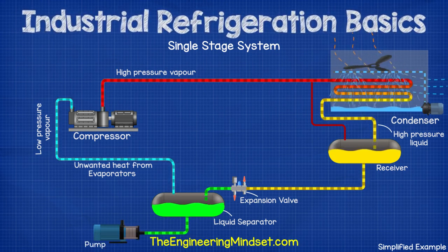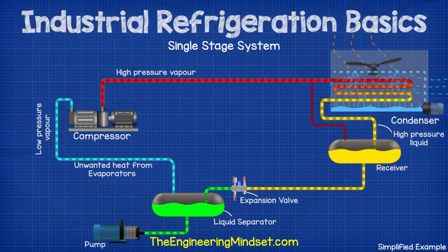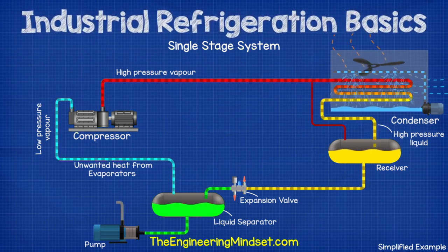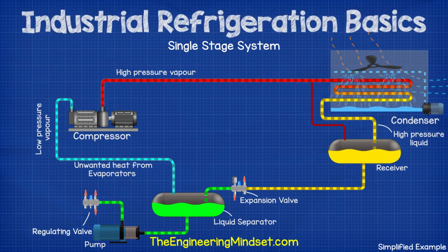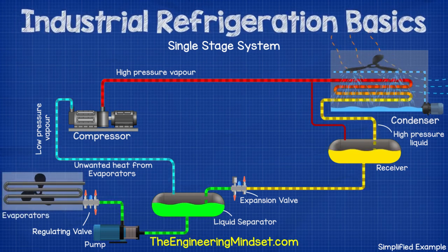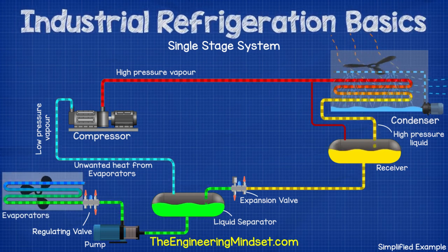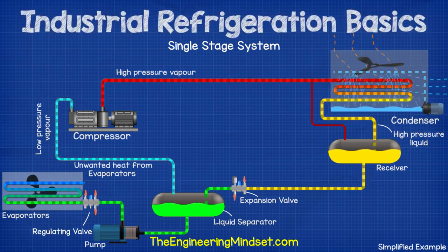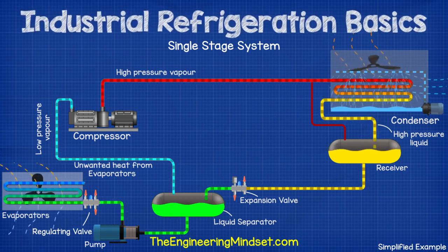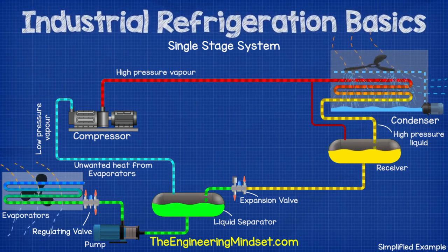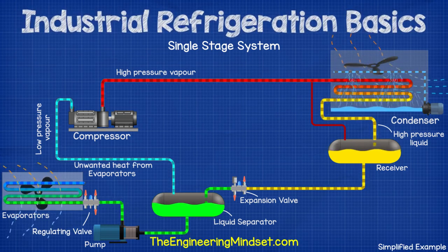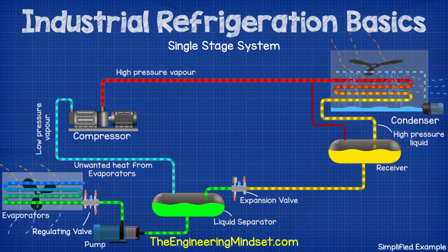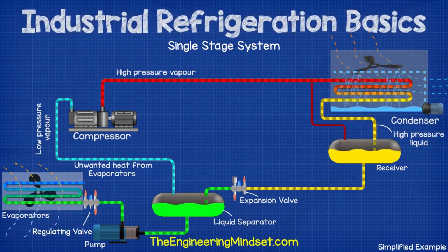These pumps ensure correct circulation rates through the evaporators as the cooling load varies. The refrigerant is then pushed to the expansion valves of the evaporator, which regulate the flow of refrigerant into the cooling load. The cold refrigerant enters the evaporator and passes on the inside of some pipes inside the evaporator, and the fan blows the warm room air across the outside of these tubes. The cold refrigerant absorbs the heat, so the air leaves much cooler and thus provides cooling to the space.